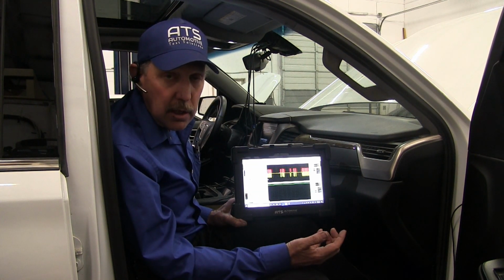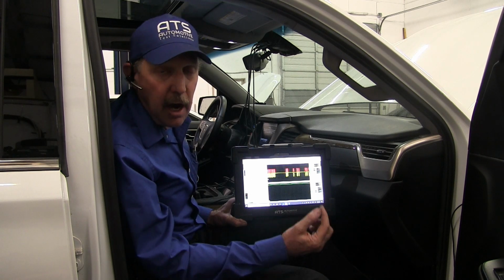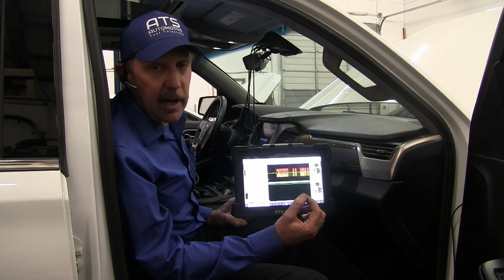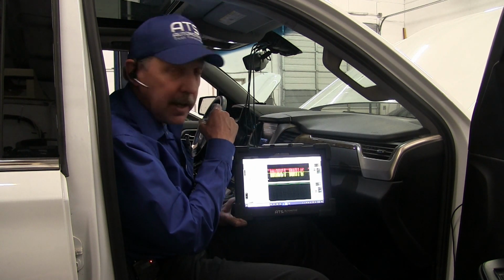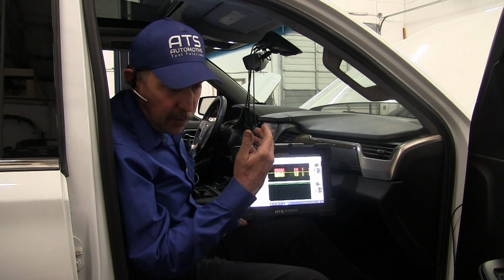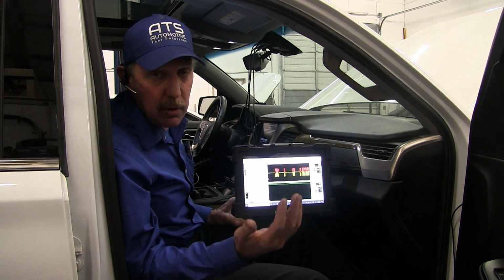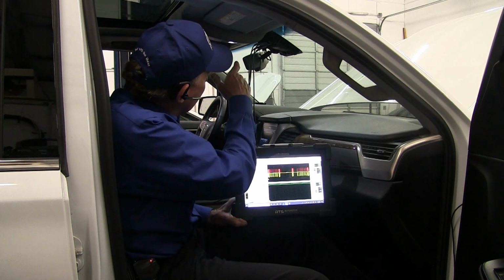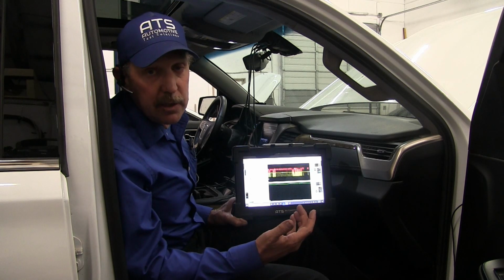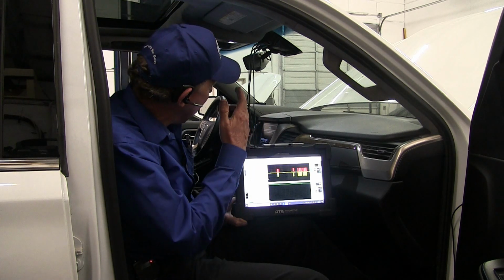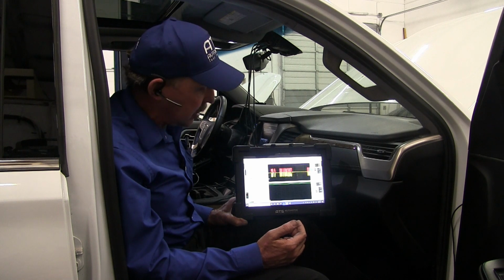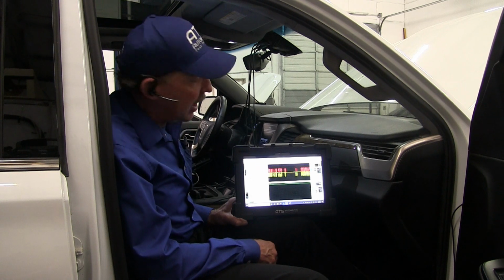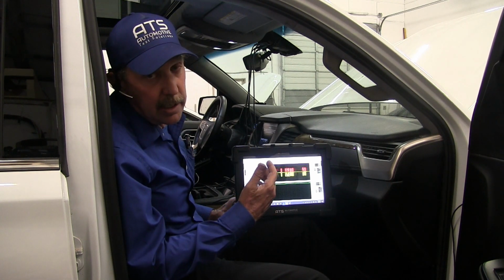So what I want to do is go to the DLC off of pin 1, because pin 1 is where GM LAN is. I'm going to take a wire from pin 1, which goes into a bridge or a comb and then goes all over the car, and I just want to bring the wire up to here and see what's going to happen. I want to get that wire back on communications to see if we're going to fix our problem or not. But this definitely does not have the GM LAN going into this system.